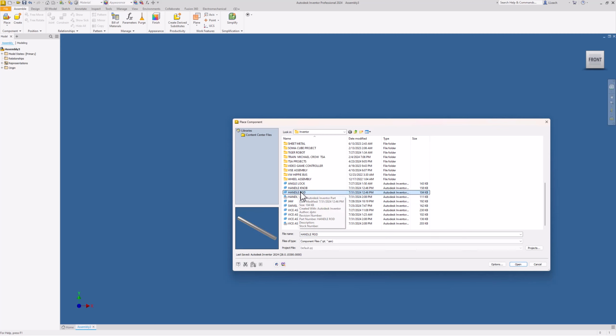and then I want to constrain the sides together so that they're flush. So I'm going to go to constrain. I'm going to click on this flush where this arrow is coming out, and this surface, this arrow is coming out. Hit apply. Now notice I can't lift it up or down or left or right, but I can move it front to back. But notice that this part will go through this part, which that's not what we want, right? So we want it to only go to here and then stop when it smacks into that back wall. Same thing in the front.